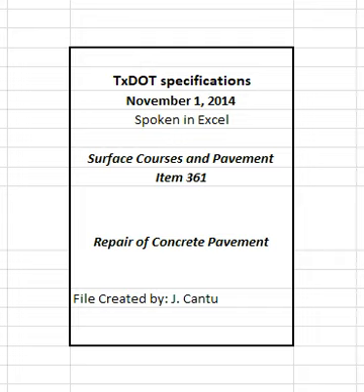Use tie bars to restore the continuity of the concrete pavement. Demonstrate, through simulated job conditions, that the bond strength of the epoxy grouted tie bars meets a pull-out strength of at least 3/4 of the yield strength of the tie bar when tested in accordance with ASTM E488 within the epoxy manufacturer's recommended curing time. Increase embedment depth and retest when necessary to meet testing requirements. Perform tie bar testing before starting repair work.